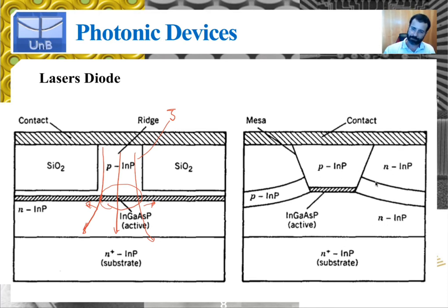So it takes a much larger fabrication effort in order to fabricate this device, because the active layer is only here, and you have additional p-type semiconductors and n-type semiconductors deposited on the sides here, and here, right? And you have an n-type semiconductor here, right? So this would also be a p-type indium phosphide, and this would be an n-type indium phosphide as well.